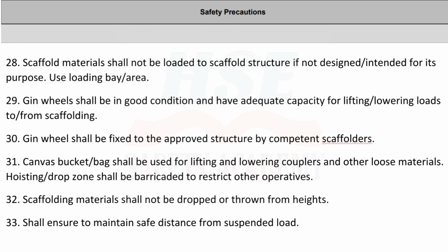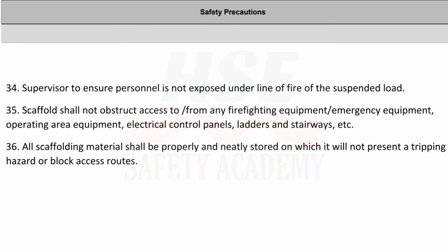Hoisting drop zone shall be barricaded to restrict other operatives. 32. Scaffolding materials shall not be dropped or thrown from heights. 33. Shall ensure to maintain safe distance from suspended load. 34. Supervisor to ensure personnel is not exposed under line of fire of the suspended load.